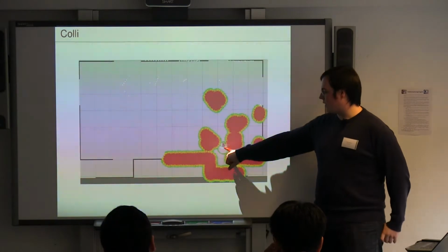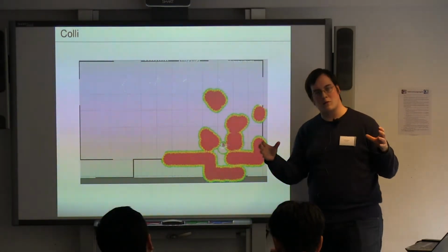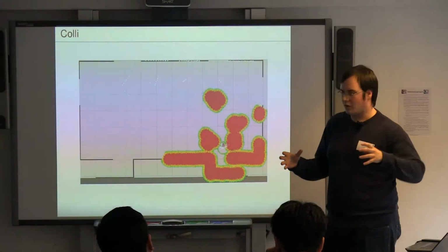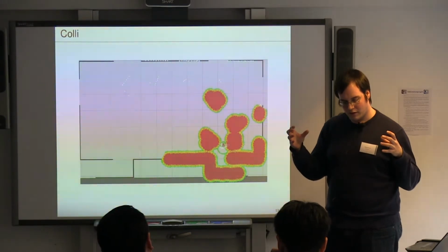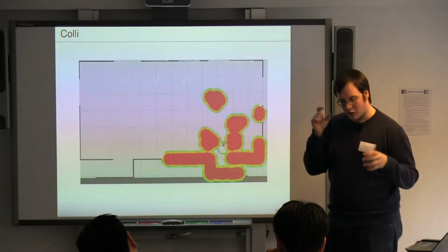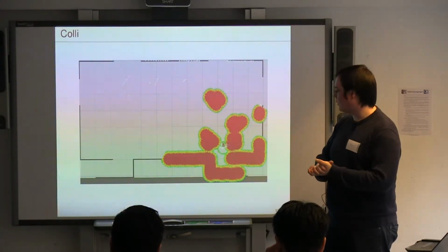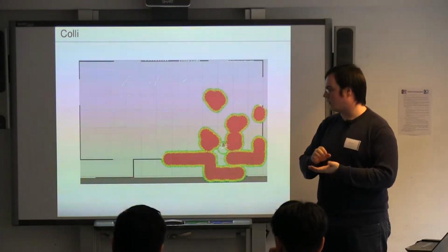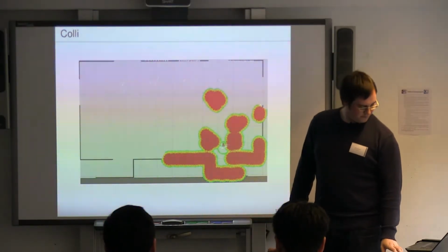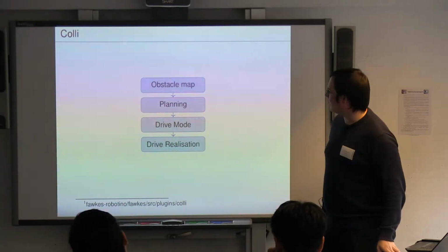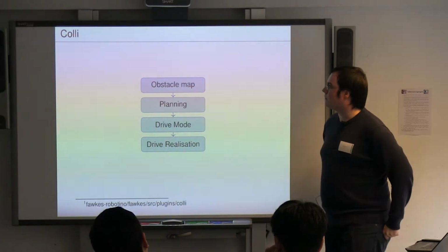And what you typically do is, for each laser data, you extend your laser data by the robot size, so that in your comparison you can think about the robot as a dot, and your obstacles are extended by the size of the robot, so that you just need to compare a dot against a plane. So, how do we get there, and what do we do during that?